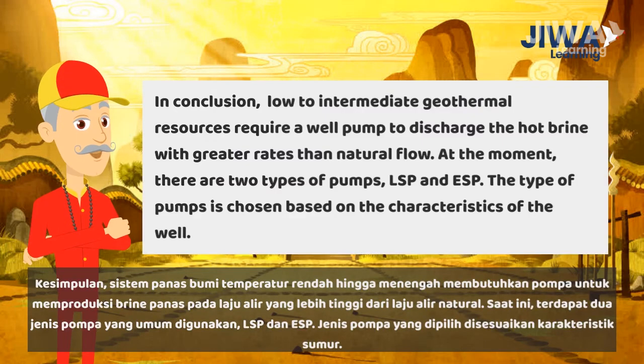In conclusion, low to intermediate geothermal resources require a well pump to discharge the hot brine at greater rates than natural flow. At the moment, there are two types of pumps: LSP and ESP. The type of pump is chosen based on the characteristics of the well.